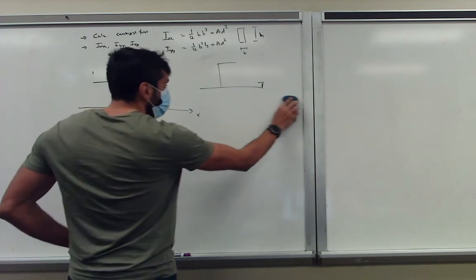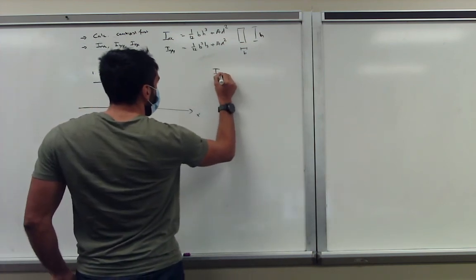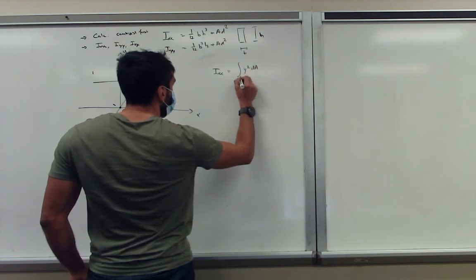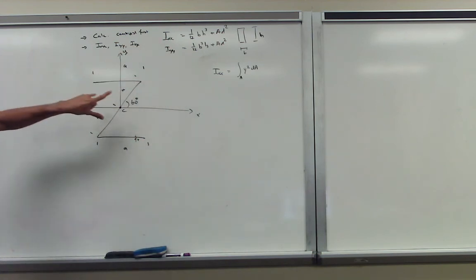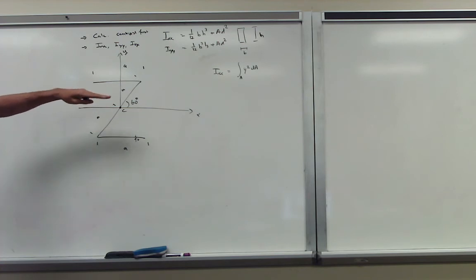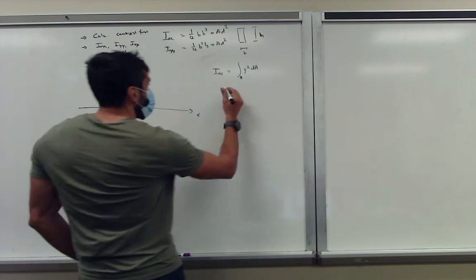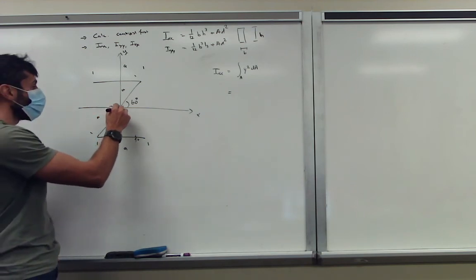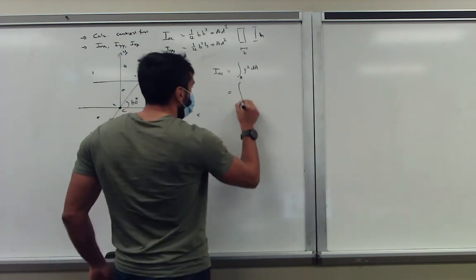What you have to do is, you have to start off, in this case, from the integral formulation. So recall the integral, Ixx is equal to the integral of y squared dA. So this is for the web part. For the top flange and bottom flange, we can still use this one because it's still basically a rectangle on its belly, horizontal, and then we do a superposition using standard terms. So okay, let's start with the inclined version. So in this case, what's y equal to? And then, of course, you have to always calculate with respect to the centroid. So your bounds must be determined with respect to the centroid. So we know we're going to travel from minus A to A. So we already have our bounds.